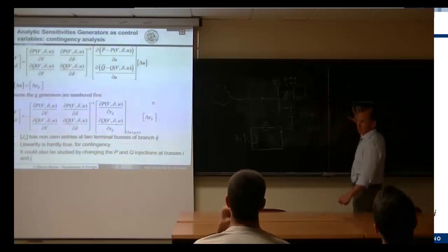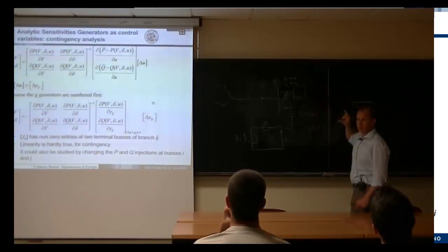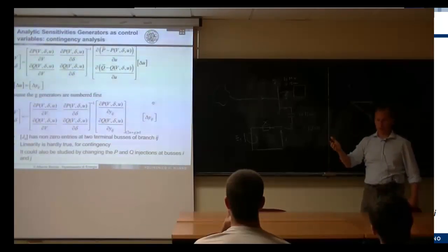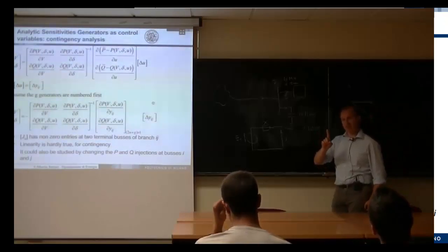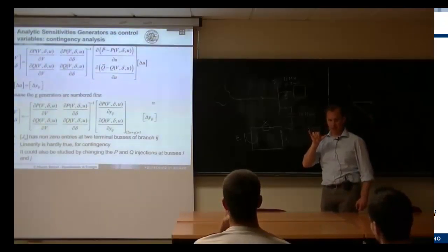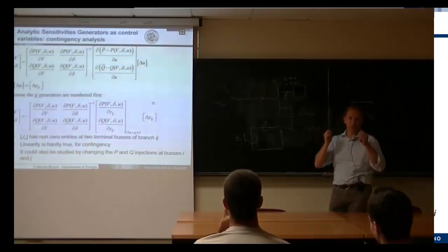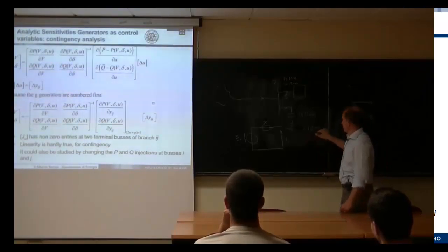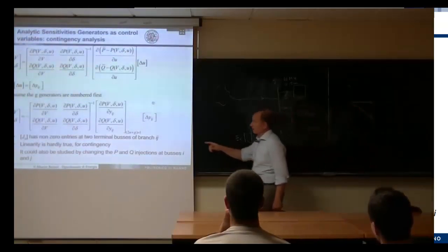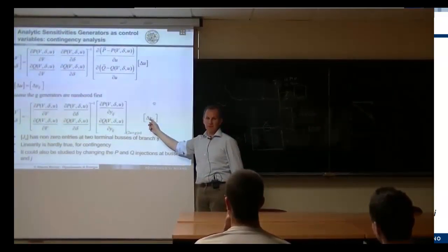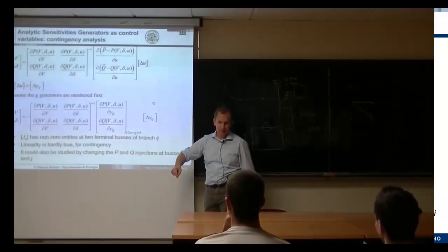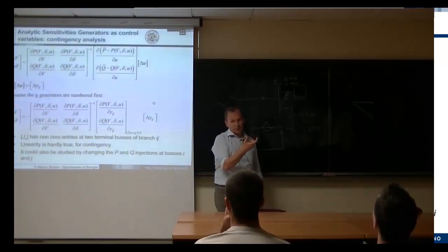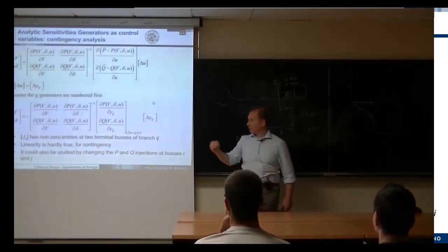have your large power system and you want to remove one branch, this is the so-called n-1 security analysis, it's a linearization. It doesn't work because it's a large perturbation. This is a large perturbation. You lose an electrical line. But it can give you an idea. So removing a line means that you move from the admittance of that line to 0, right? So you apply a delta y, which is exactly the admittance y of that line, and you find out